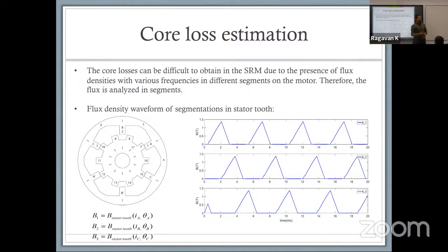Why? What we were trying to do was calculate the core loss inside the motor. We were trying to figure out how much loss we are going to get in order to calculate the efficiency in our simulation model. Because when you do a simple Simulink model, it's easy to calculate copper losses. It's I, you know what R is. You can do a 4-probe test. You can basically do an LCR meter or something and measure the resistance of the winding. I squared R gives you the copper loss.